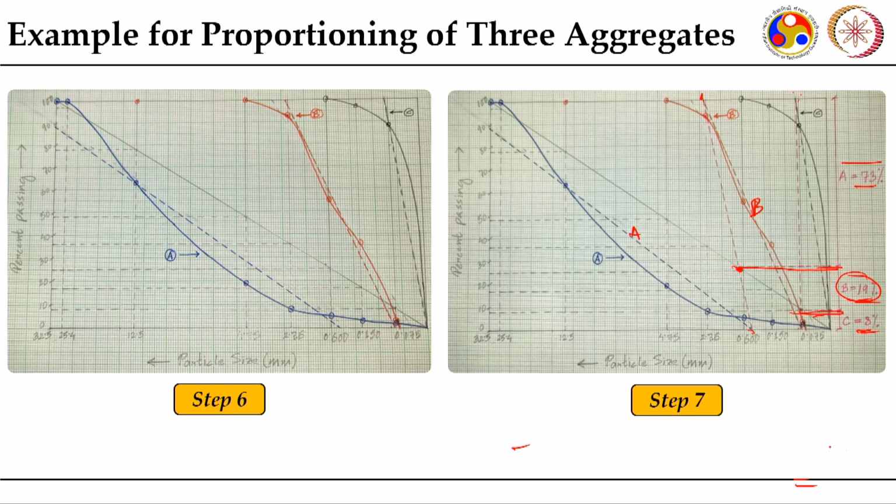So this is the initial step which we normally do whenever a mix design of these unbound granular courses is to be done, that you look into the blending of the aggregates, in what best manner different stockpiles of aggregate can be blended to achieve the desired target gradation, which is suitable for use as a sub-base course or a base course, under which different gradations are specified by IRC and MORTH. Thank you.